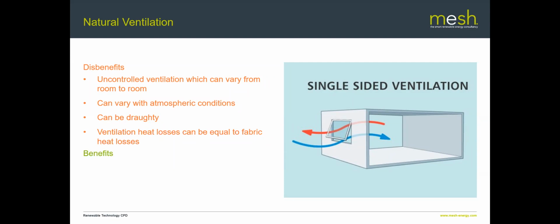Benefits of natural ventilation: obviously there's zero running cost, or zero direct running cost. With natural ventilation, you're not running a fan, you're not having to run any sort of preheaters, you're not having to change filters, you're not having to do anything of that kind of stuff. So it's got zero direct running cost. Obviously there's quite a significant indirect running cost from increased heating bills. It's relatively easy to specify. It's about making sure the right ventilators are in the right place, and there's obviously no noise associated with it because there's no fans, there's no mechanical items that can make noise.